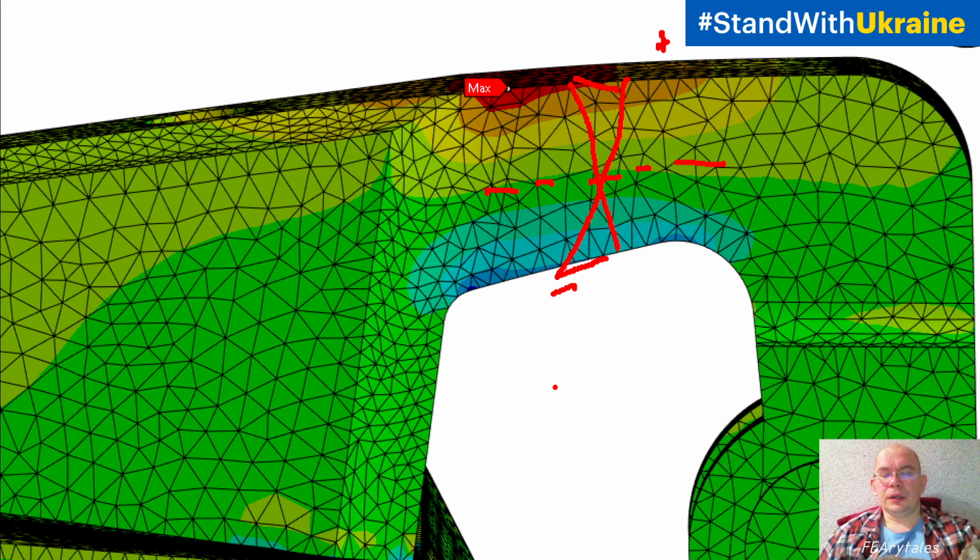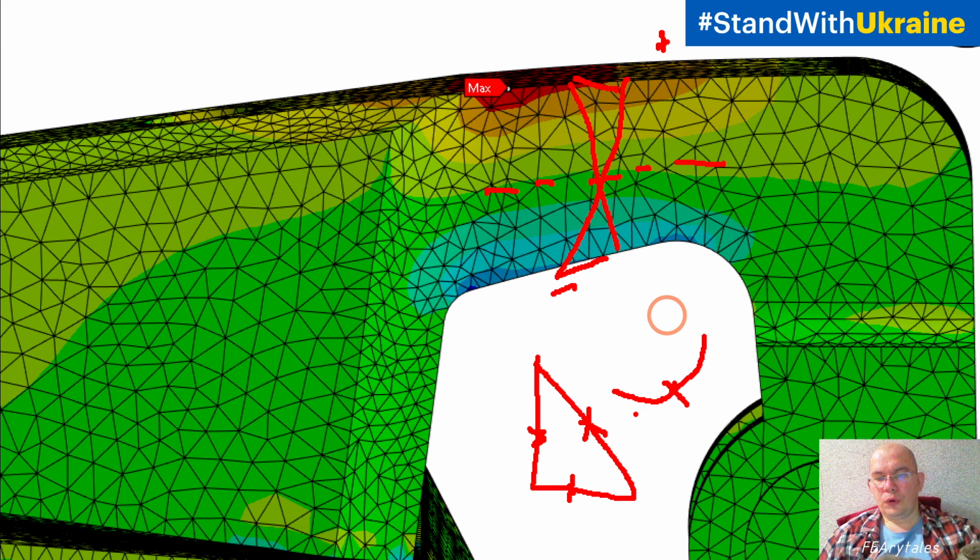And you need to understand that if we use element with a mid-side node, additional mid-side node, we see quadratic form. We use quadratic form for this element. We use quadratic distribution not only for form but for deformation description, and we see we have linear description of stress during those elements.